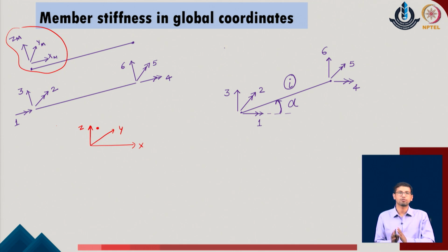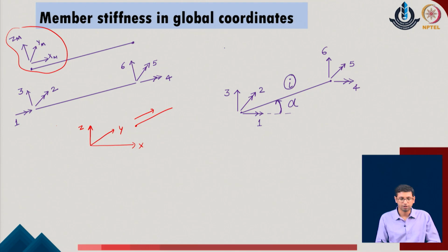One must understand that when we are talking about the grid system, most of the calculations are defined in the horizontal plane of the given system. So, that is why I have defined the x and y axis in the horizontal plane, and the z is the normal plane to the given surface. So, now at any point if you locate the given, so if I just locate it over here, at this point corresponding to the member direction, the individual degrees of freedom were defined with respect to 1, then 2 and 3 in the given system.